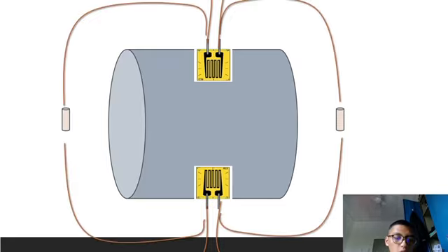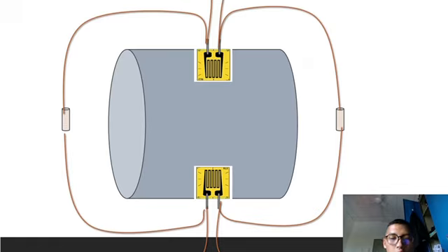So this is a functionality. Strain gauges operate based on resistive and geometric effect. When the material they are attached to deforms, their resistance changes proportionally, and this change is amplified using a Wheatstone bridge circuit to detect even minute deformation accurately.